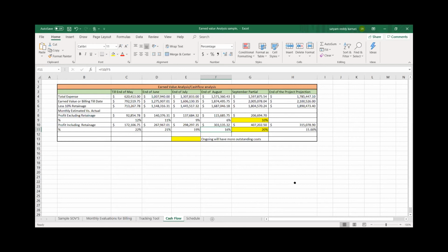Then we will perform and track the work in the field. I estimated it at 100 linear feet a day, and we ended up actually doing 120 linear feet a day. So he's actually capturing 20 more linear feet. We will use that data on similar projects. If we bid a similar project in the future, we will use that data and improve ourselves. Next time I'll use roughly 110, because we did 120 on the similar project.